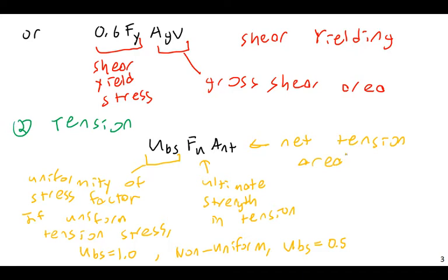So what I have laid out in this slide and the previous one are the various ways that we get capacity in block shear. So in block shear rupture, the tension plane we only consider for fracture, but the shear planes, we'll calculate their capacity for both fracture and yielding, and basically go with the smaller one effectively. So these are the different pieces of the overall equation that we find in Chapter 4 of the AISC Steel Manual. Let me then next go to how all of these fit together in the actual code.